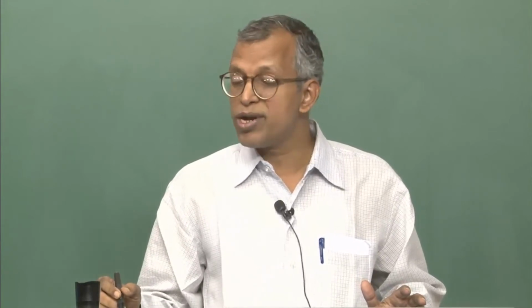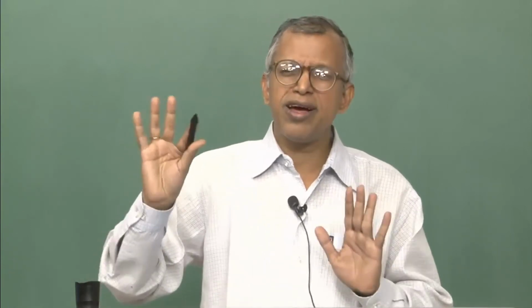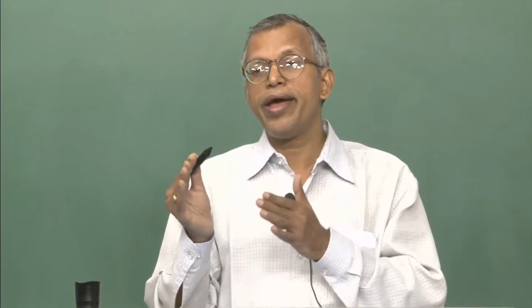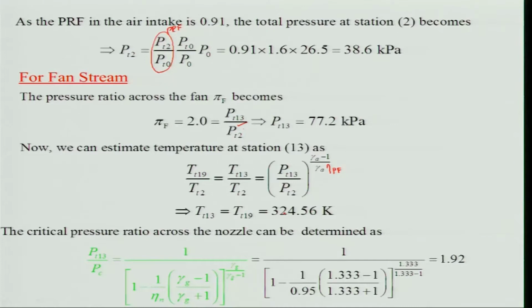Mostly it will be flying at subsonic flow, but even in fighter aircraft people are nowadays using turbofan engines with very low bypass ratio, not a high bypass ratio of 5, which is generally used for long range passenger aircraft, moving in level flight at a flight Mach number of generally around 0.85. But here we are assuming the nozzle to be a convergent nozzle, and that assumption I had not mentioned, but whenever you are doing this you need to state it, since it is not given in the problem, am I right.